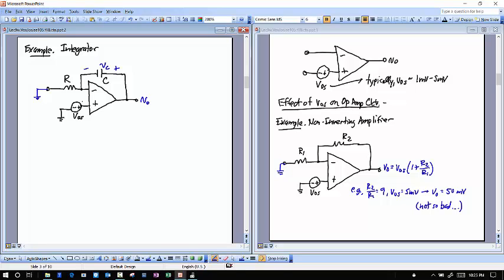And it's not what it's going to be because, again, I have this voltage at the positive terminal of this op amp. And if this is negative feedback, which is what this is, then the voltage at the negative terminal, because it is an op amp, and we're saying ideal in all respects except for the offset voltage, is also going to be equal to VOS. And if the voltage at the negative terminal is equal to VOS, that means I've got a voltage across this resistor R, which means a current is going to flow, which I'll call I1, going through this R.